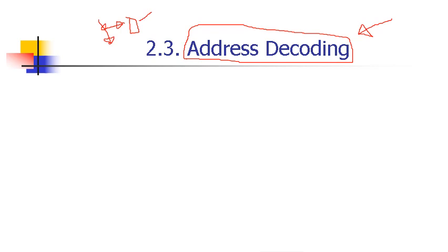Besides, memory chips provide a fewer number of address pins than the processor can provide. For example, a memory chip may require 10 address pins, if it's in the 1 kbyte range. Your processor provides for each memory location 20 bits. So these 20 bits have to be decoded to produce the required 10 bits of the memory device. So we have to decode the address in order to be able to communicate with more than one memory chip